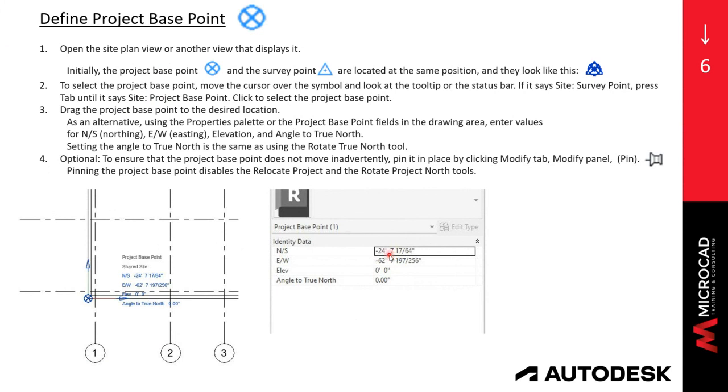Once you have it placed, my advice is to pin it. You need to go to the Modify tab, in the Modify panel, and use the Pin tool. Pinning the project base point will disable the Relocate Project and the Rotate Project North tools. Okay.